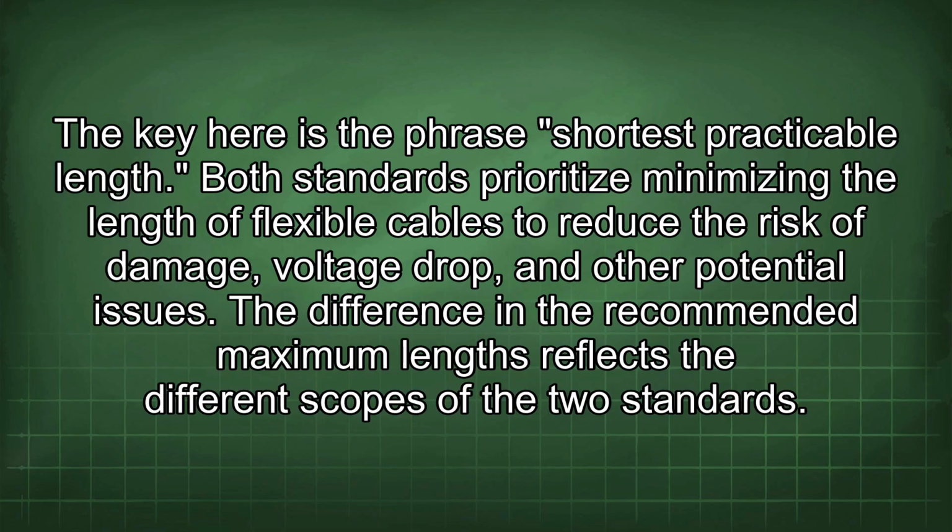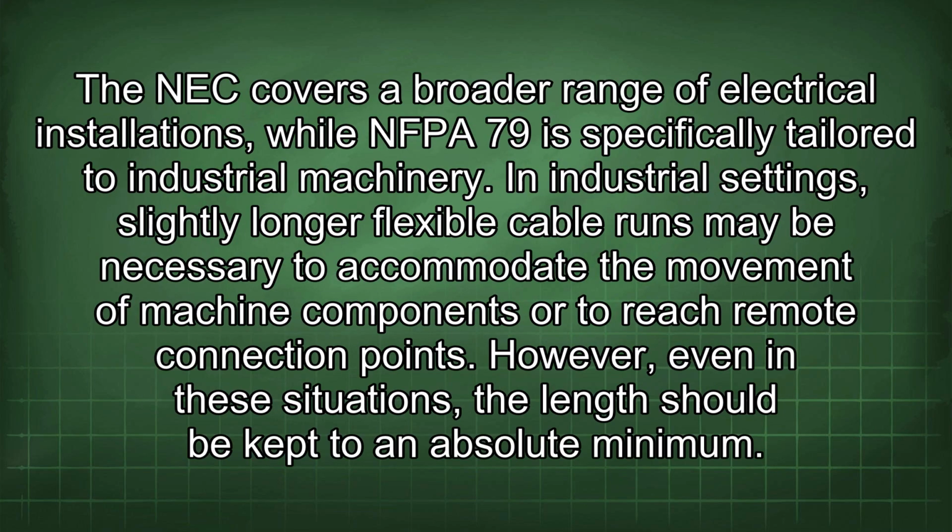Both standards prioritize minimizing the length of flexible cables to reduce the risk of damage, voltage drop, and other potential issues. The difference in the recommended maximum length reflects the different scopes of the two standards. The NEC covers a broader range of electrical installations, while NFPA 79 is specifically tailored to industrial machinery. In industrial settings, slightly longer flexible cable runs may be necessary to accommodate the movement of machine components or to reach remote connection points. However, even in these situations, the length should be kept to an absolute minimum.